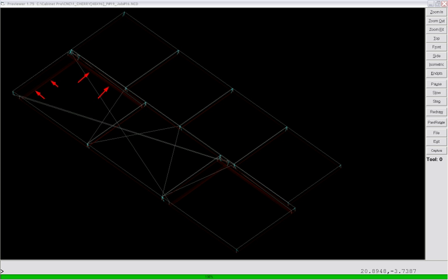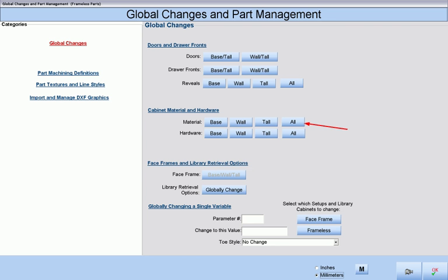And when we run our simulator, we will see our CNC machining has been automatically adjusted as well. Remember, we deleted all machining such as system holes, shelf holes, hinge plate holes, and numerous dado cuts so that we can concentrate on just 2 dado cuts that will demonstrate material independence. Note that the dado cuts have been adjusted to fit the parts going into them with multiple passes since we are still using the same 1/4 inch tool for both of them.